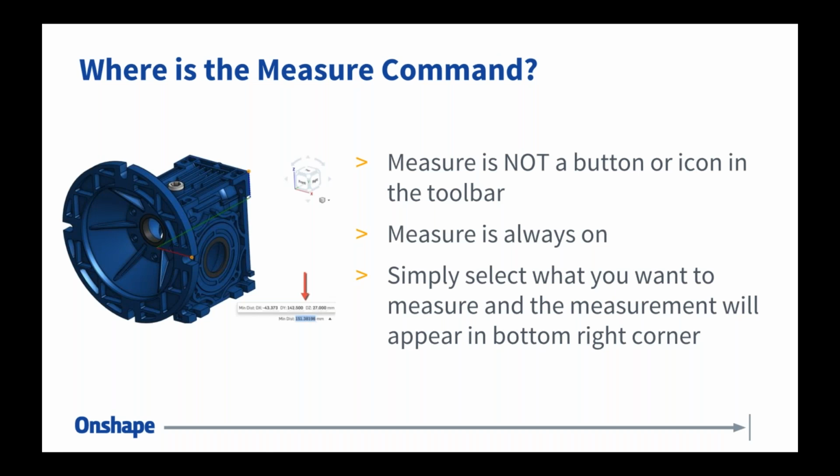So that's the first thing, probably one of the most important things I would stress to all those new users out there. One of the first questions I get asked is, I've imported a model. How do I tell what diameter this hole is? Right. So measure is going to be one of the first things that you're going to use as a new user, and it's important to understand how it works. And I'm going to give you an example of this in just a second, so bear with me. But that's the key thing. It's not a command in the interface. You simply select the thing that you want to measure, and the measurement will appear in the bottom right corner.